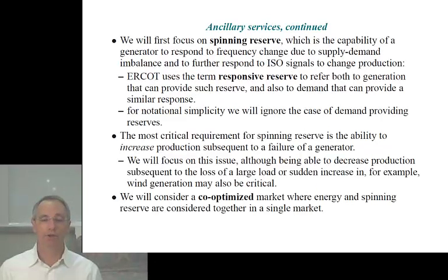It's the capability of a generator to respond to frequency change due to supply-demand balance, and then to further respond to ISO signals to change production. As it happens, ERCOT uses the term responsive reserve to refer both to generation that can provide such reserve and also to demand that can provide a similar response to generation providing spinning reserve. For notational simplicity, I'm going to ignore that case of demand though.